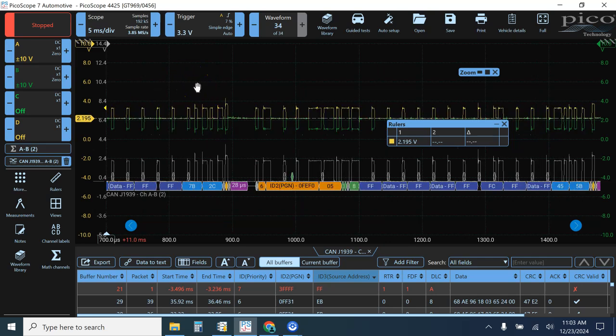So you can see, even though we had the same kind of failure, resistance to ground on a device, it really matters what the device is and how much current it draws. From device to device, you might find different results. And it may depend on how much resistance it has. In this case, I had a couple hundred ohms of resistance on the knock sensor ground. That was enough to really change the waveform and drive it way up, as the knock sensor's 12-volt power supply was basically partially shorting back into the CAN bus. And I've seen this before on a lot of various devices.